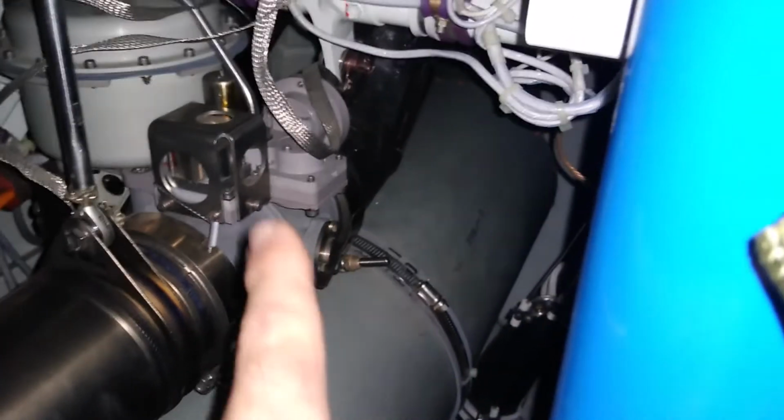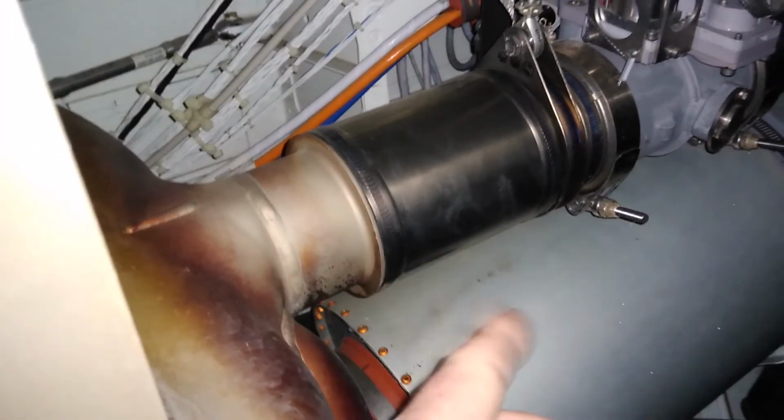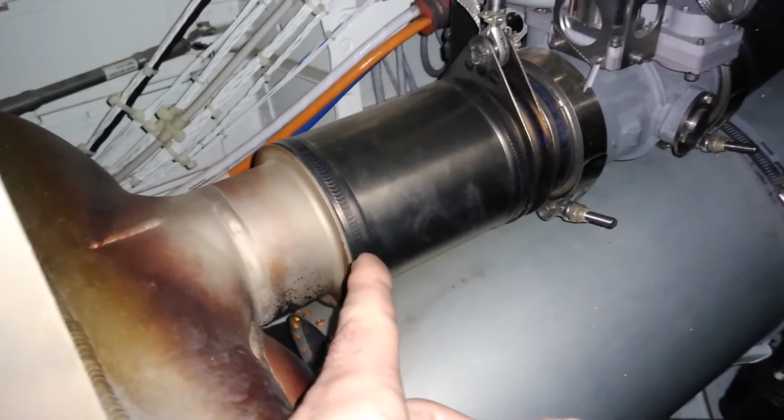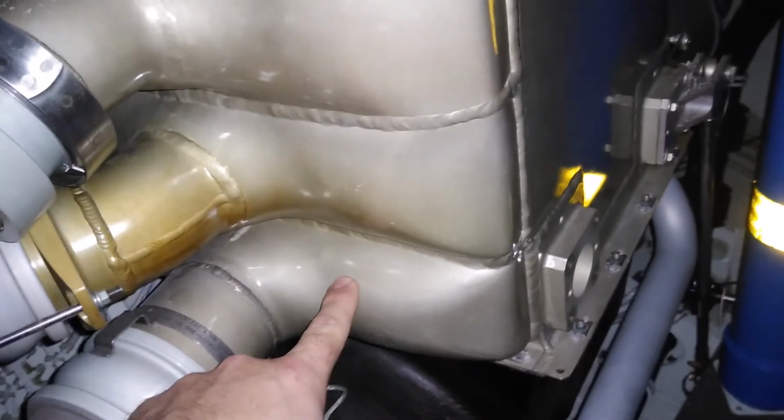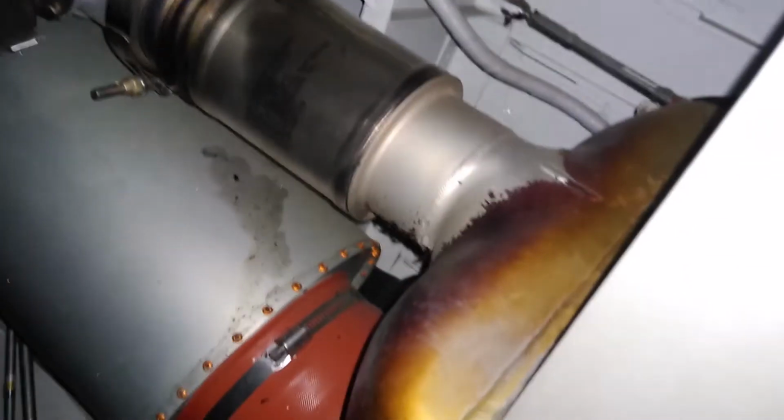And now looking further back, we see here that is the inlet of bleed air with a control valve. Bleed air from the engines or the APU. Bleed air coming into the primary heat exchanger, which is the one on the bottom over here. Primary again, because that is the first heat exchanger that bleed air sees. Here's the one on the other side. Bleed air coming in to the heat exchanger.